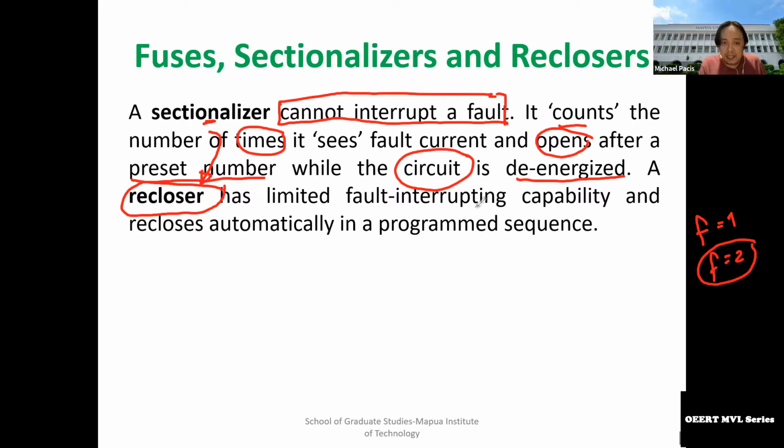Okay, so it has a limited fault interrupting capability and recloses automatically in a program sequence. So it means it has an allotted time of operation. Typically the time of operation is 1 millisecond to 2 milliseconds.